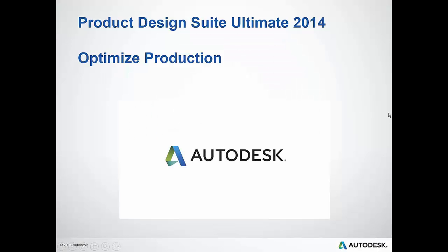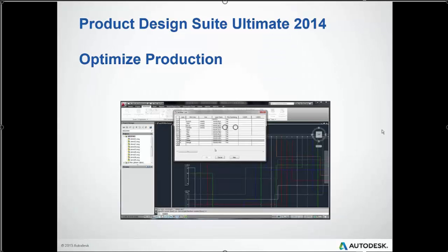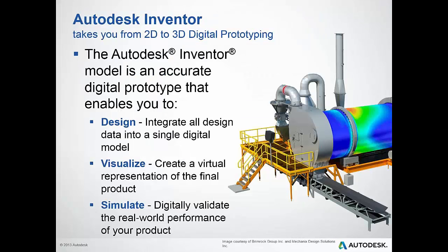So what's nice about that is you notice that what it did is it just shot a straight line from one area to another. And it's the same thing with the tube, rubber hoses, or all those different types. So I can actually know point A to point B, and then I can physically route myself as a designer how that tube is going to fit in there, and the bends, or whether it's a harness, where I'm going to put wire ties, where I might screw it to the side and support it, whether I need to put heat guards on it. So at one point in time, you're designing the schematic, an electrician, and at the other point in time, you're installing this harness into a product. So it integrates that process, so it makes it a lot easier.